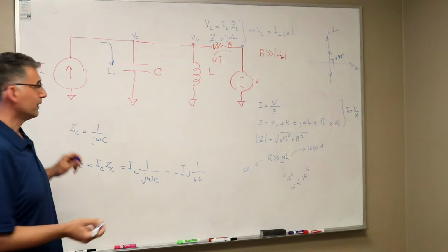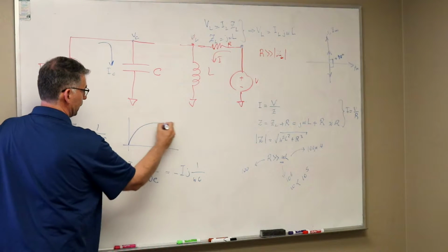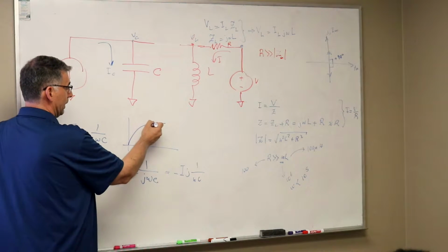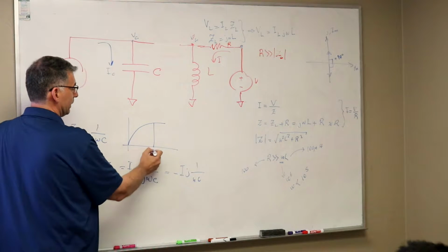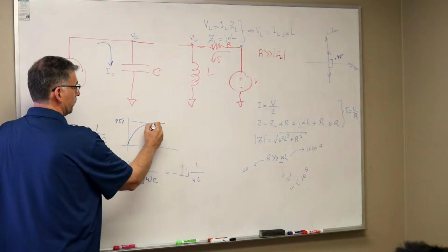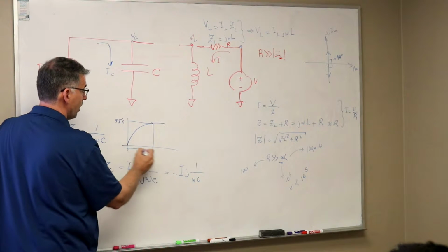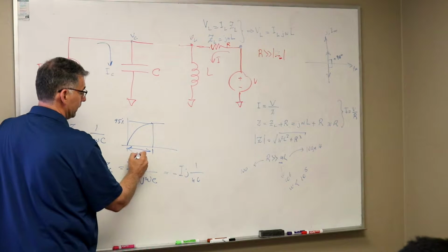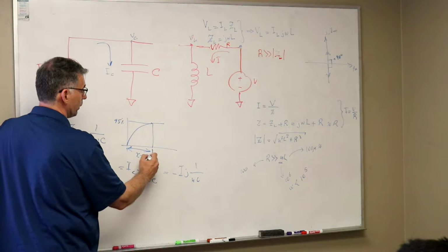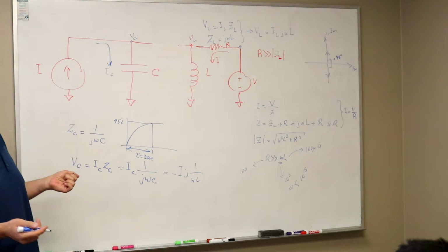Right. So in the case of the capacitor, we looked at this charge time, and we actually looked at the 95%, when the voltage reached 95%, and then we looked at this time, right? And this was supposed to be equal to 3RC, and from there we could figure out what C is. Okay?